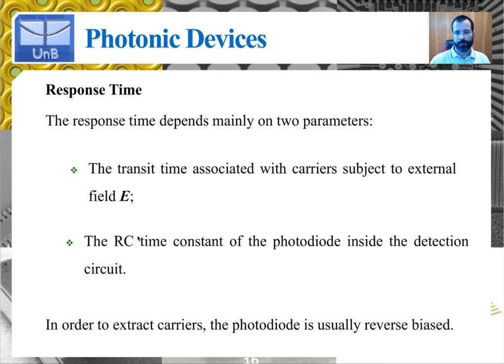In our next lecture we're going to discuss the polarization circuits, but basically the way that the device is polarized is by placing it inside a circuit which has a load resistance, and sometimes the voltage across this resistance has to be amplified by an op amp or other types of amplifiers, which will also have an input resistance.